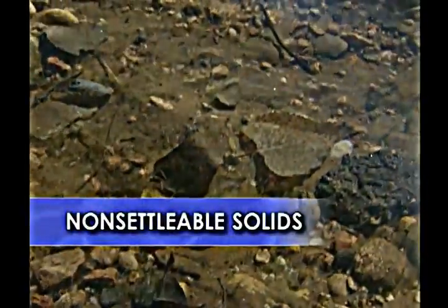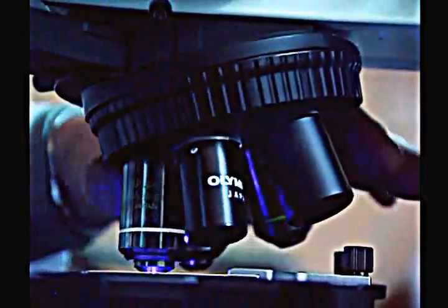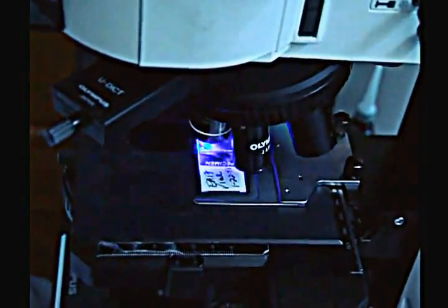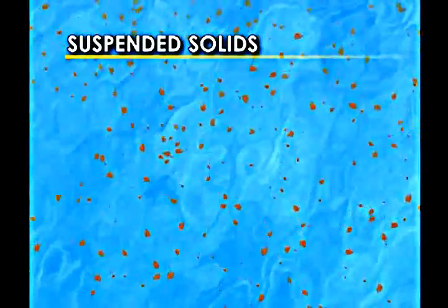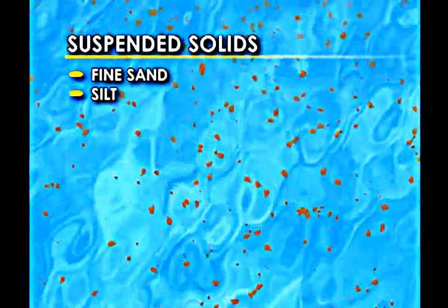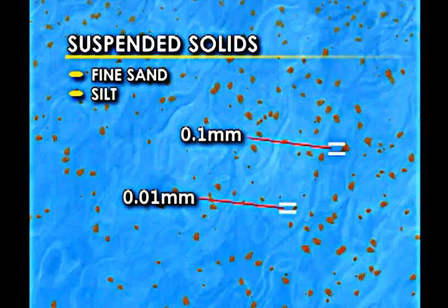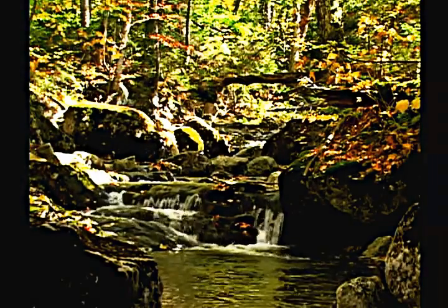The particles that cause turbidity consist mostly of non-settlable solids. These particles typically do not settle out of water because of two factors. One is particle size. Fine silts, protozoa, bacteria, viruses, and natural organics are microscopic. Non-settlable solids are broken down into three types. Suspended solids, which include fine sand and silt, range in size from 1/10 to 1/100th of a millimeter in diameter, or perhaps smaller. They are held in suspension by the natural action of flowing water.